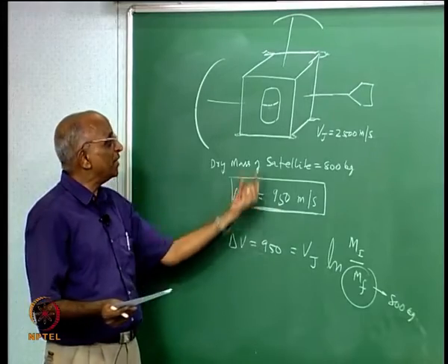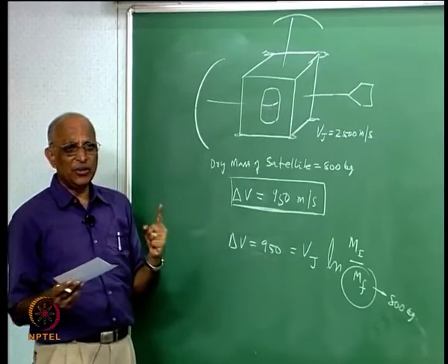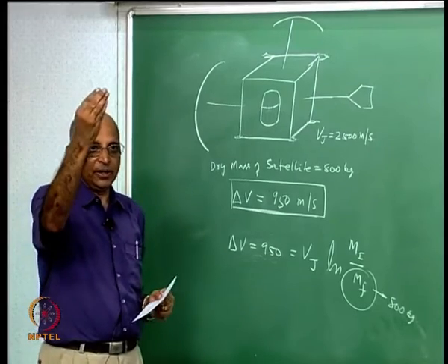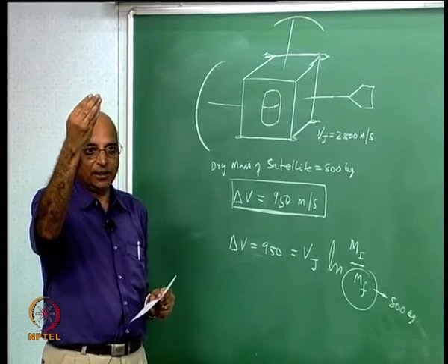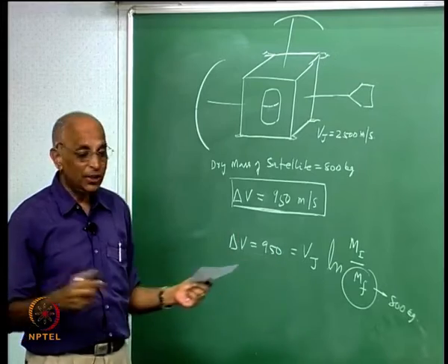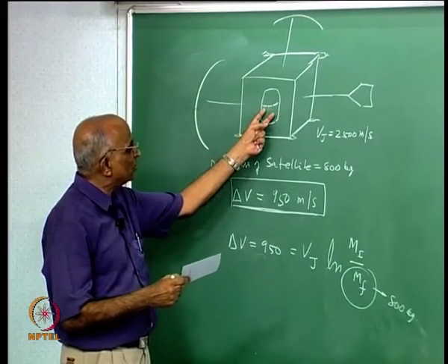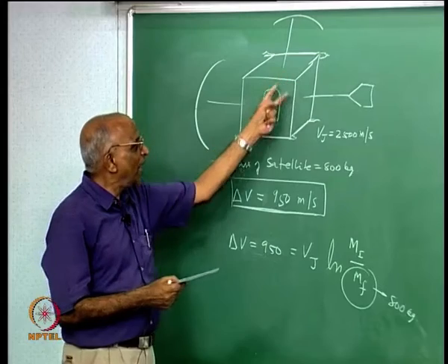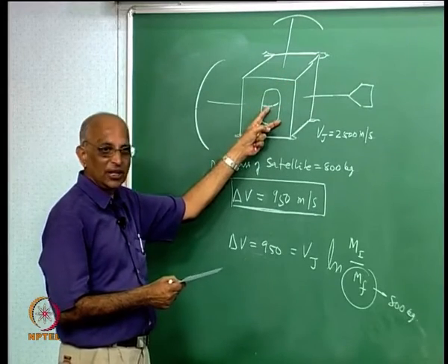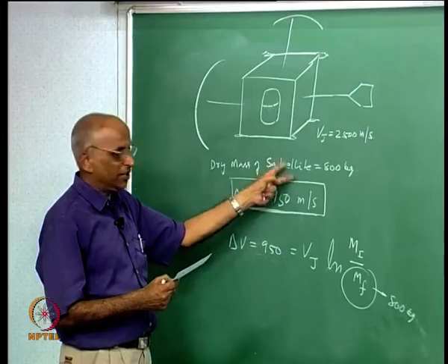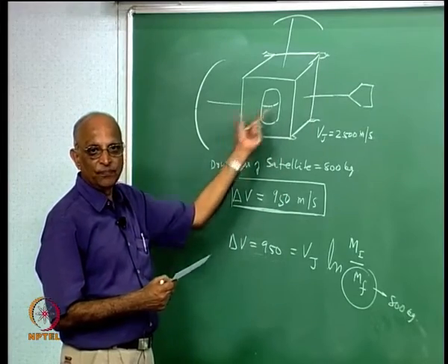If I want it for 1 year, I can have this, and that is why whenever we read the newspaper, somebody says the initial orbit has a significant error, and therefore the lifetime of the satellite comes down. Why does it come down? Initially itself I take some of this fuel to give me the orbital velocity or the corrections, and therefore my station keeping of the satellite and the attitude and orbit corrections are decreased because I have less amount of fuel.